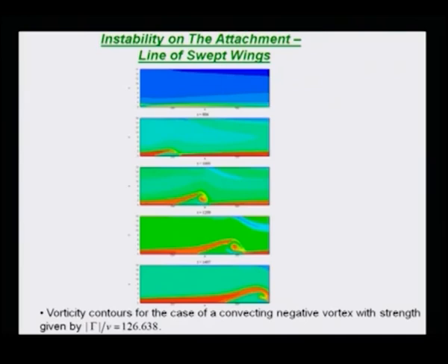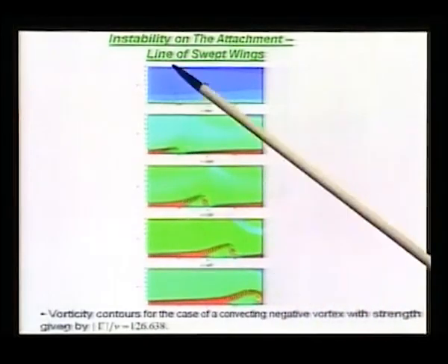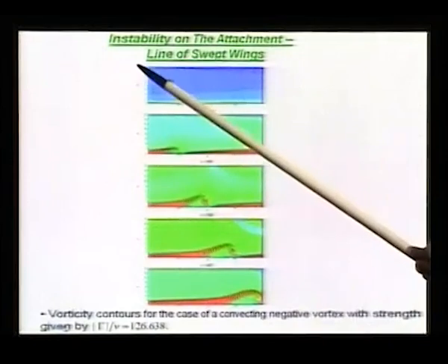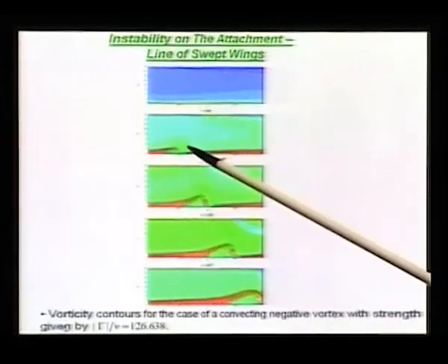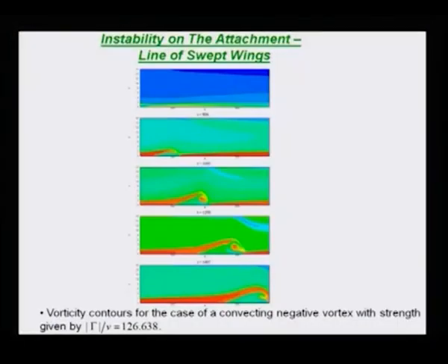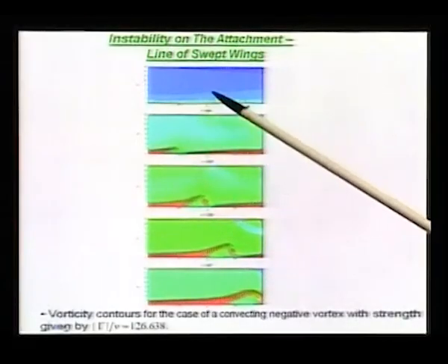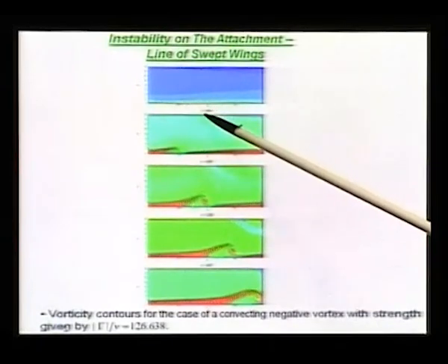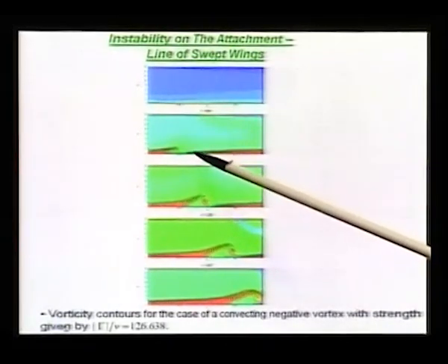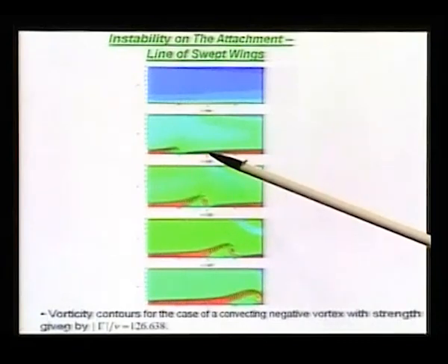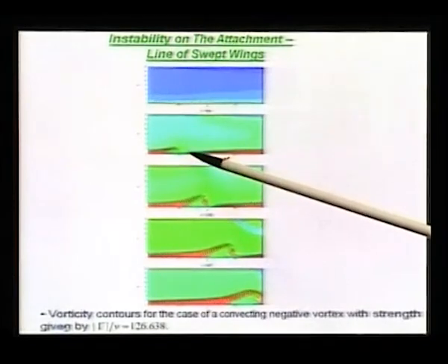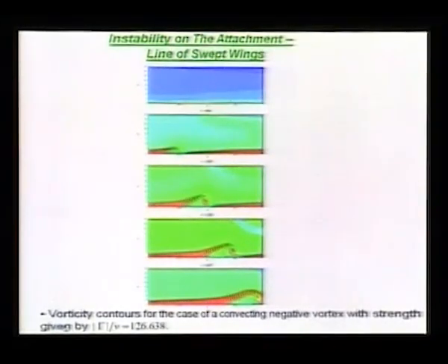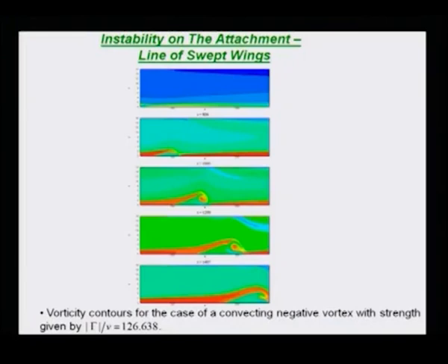Now, you can see what is happening. We are seeing the vortex. This is now outside the range. Here the vortex is somewhere here, and this lifting up is happening behind. So, you can reason out that the vortex must be here, and then you can also see that just ahead of the vortex the boundary layer thins down. So, you can see the vortex must be exactly on top of this. That is why you do not even need to provide the arrow.